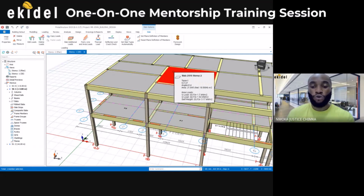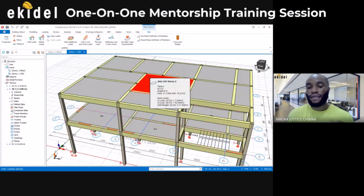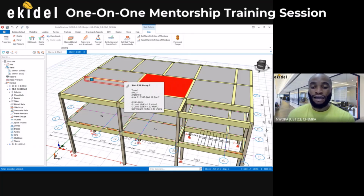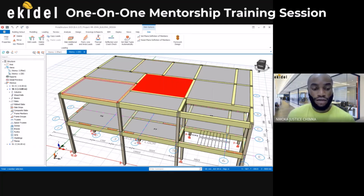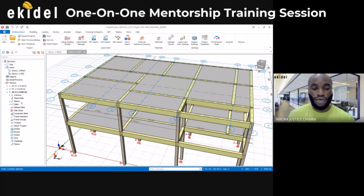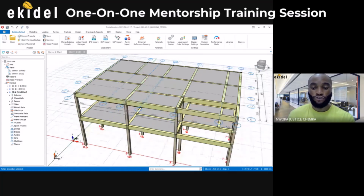So if you have any load, but if it's not a concrete roof, then we go and remove the slabs. So we can just remove this. Right now, I am assuming that we are dealing with roofing sheets and not a slab roof, right? Not a concrete roof. So with that now, I'll make sure I'm on story 2 now. Come to story 2 here. Double click on it. It will now be on story 2.